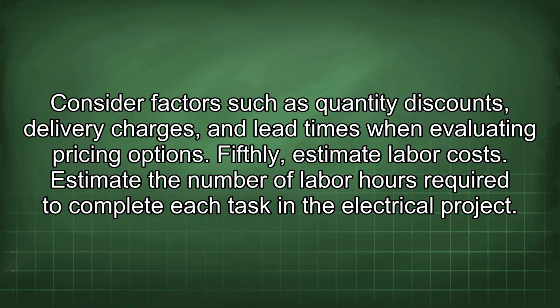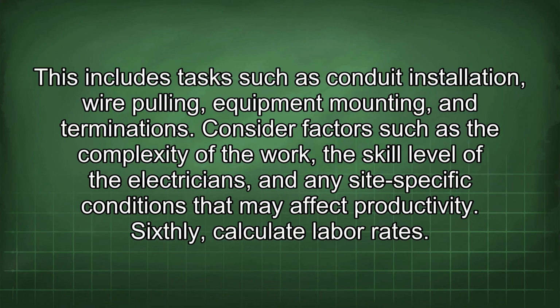Fifthly, estimate labor costs. Estimate the number of labor hours required to complete each task in the electrical project. This includes tasks such as conduit installation, wire pulling, equipment mounting, and terminations. Consider factors such as the complexity of the work, the skill level of the electricians, and any site-specific conditions that may affect productivity.